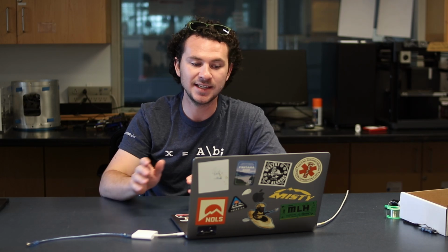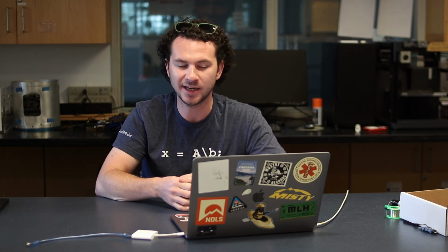A few final details: atan2 outputs an angle in radians, so we'll use a conversion factor that Arduino provides called RAD_TO_DEG to get angle in degrees. We'll also input the negative of the y component to atan2, which essentially just rotates the axes of our magnetometer so the y-axis points towards the front of the rover.